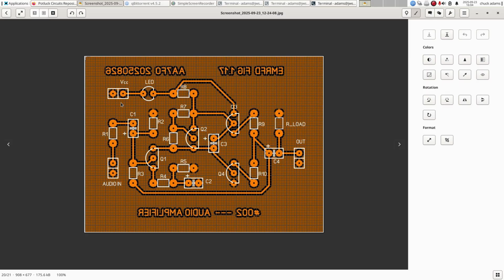And if you happen to have a very large lab supply that can do 30 volts, and you're asleep one night and you apply 30 volts across here, the LED is going to act like a fuse, hopefully. All right. There's a joke that the transistors will destroy themselves to save a penny LED.